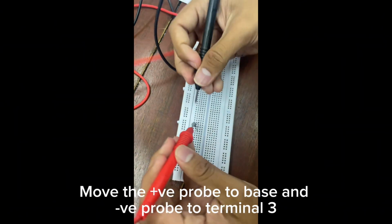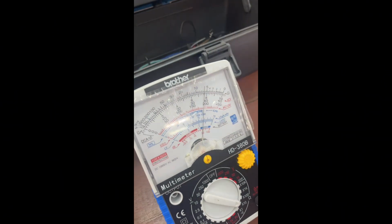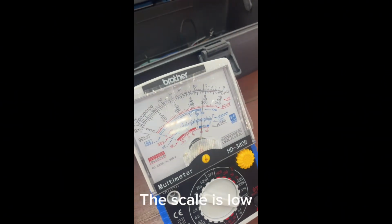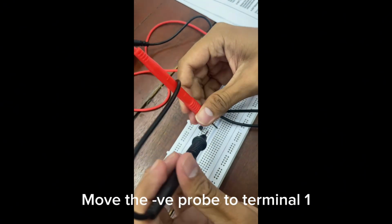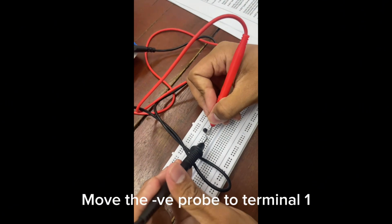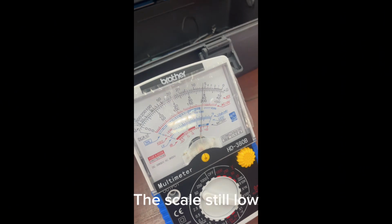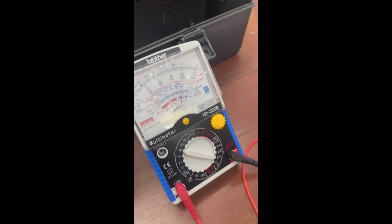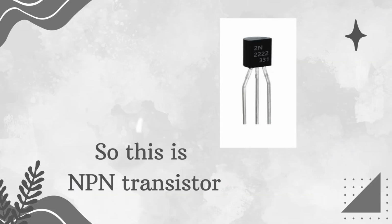Next, move the positive probe to the base and the negative probe to terminal 3. The scale is low. Lastly, move the negative probe to terminal 1. The scale is still low. So, this is an NPN transistor.